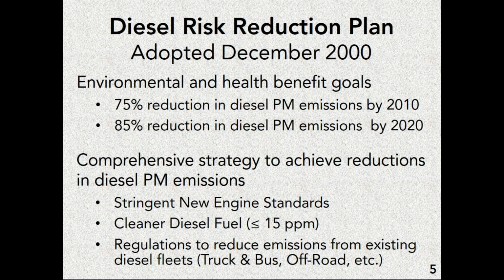The second reason why sulfur is a problem in diesel fuel is that sulfur has a tendency to poison catalysts. And a lot of the technology that is being used and implemented to make the engines run cleaner, or at least clean the exhaust after the engine has produced the exhaust, uses catalysts. So if we get the sulfur out of the diesel fuel, we succeed in two ways. We reduce the particulate load and we protect the catalysts that are also reducing the emissions, or helping to change the emissions at least. All right, so those are both nationwide.